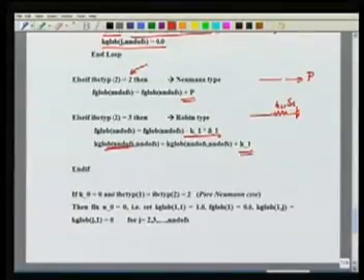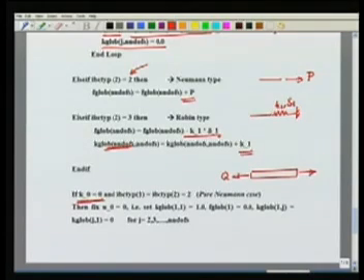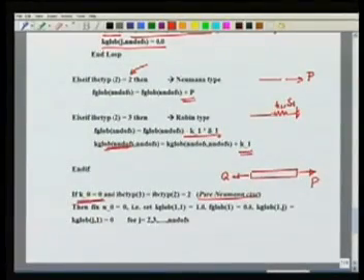One more thing that we have to keep in mind is the special case when there is no distributed spring on the structure, that is, I may have this kind of a situation. There is no distributed spring and both ends have Neumann boundary conditions, with or without point loads, that is not a problem. If my spring constant is 0, which I can check very easily, and if the boundary condition type at both the ends is 2, which is the Neumann case, this is called a pure Neumann problem.